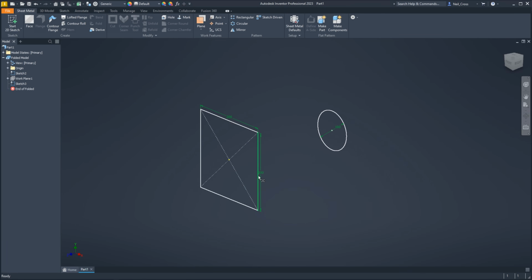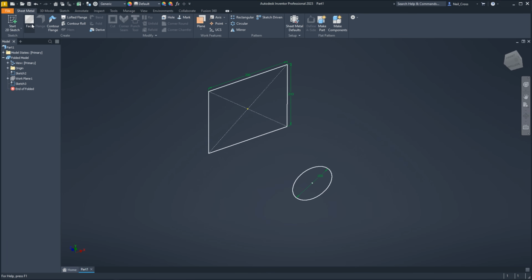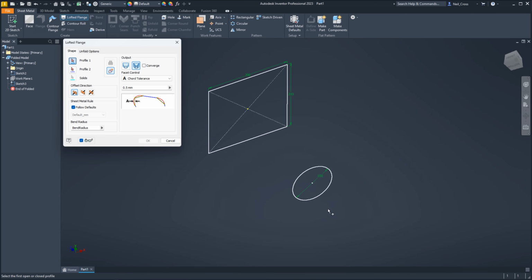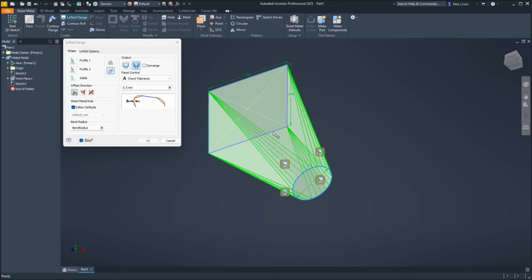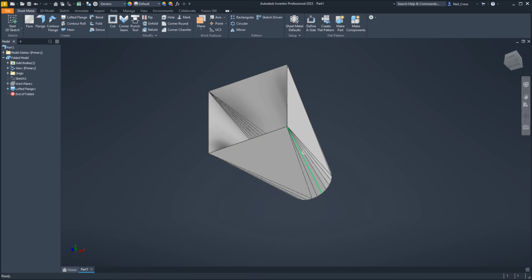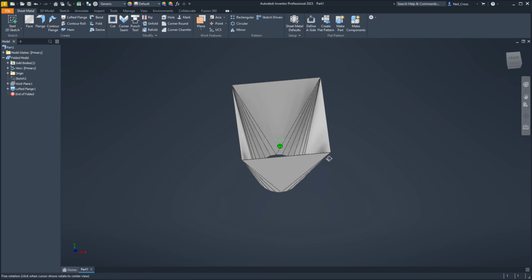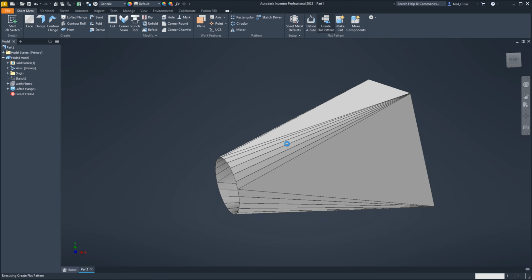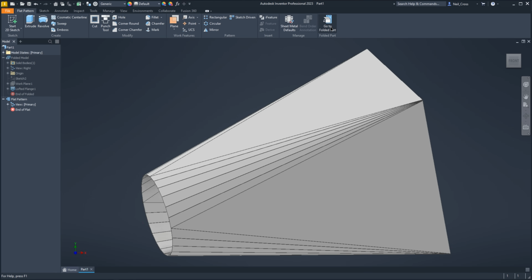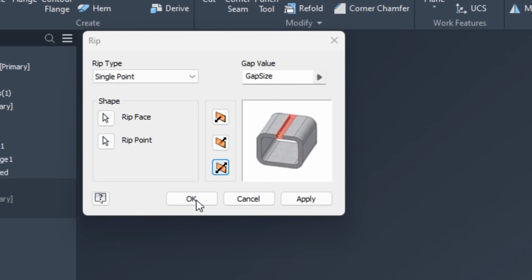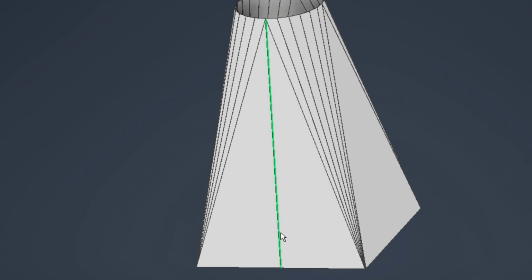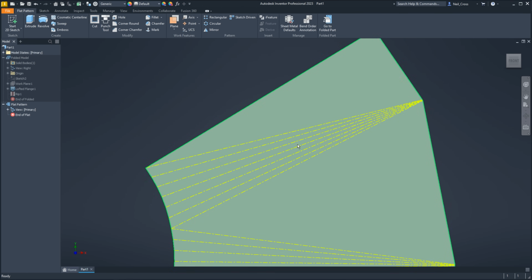Inventor, for example, has got the best named command ever, rip. So say you've got a lofted flange, squared around. In Fusion, you'd have to meticulously trim out a section of both sketches or else the damn thing just won't unfold because it's going to be one completely closed, fused body. And how much do you trim out? How much do you open up for it to properly unfold? I don't know. It's a chore. No problem with Inventor though. Just pick a point and rip it wide open. Now that's your parting line for unfolding a flat pattern.